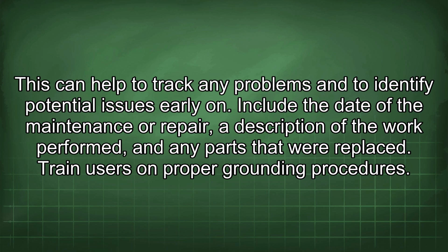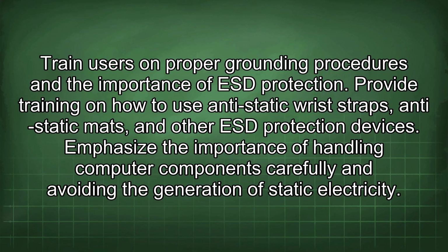Train users on proper grounding procedures. Train users on proper grounding procedures and the importance of ESD protection. Provide training on how to use anti-static wrist straps, anti-static mats, and other ESD protection devices. Emphasize the importance of handling computer components carefully and avoiding the generation of static electricity.